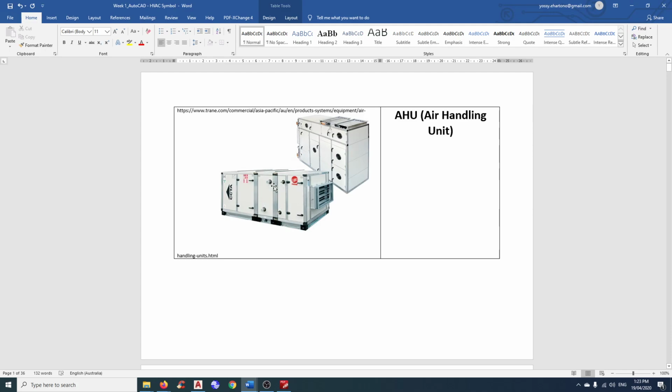As you can see here, this is the back of the air handling unit, what we call the return air plenum, or if we have an outside air intake, we call it a mixing plenum. You can see a little pipe coming out here. It looks very small to me, so it might be heating water.